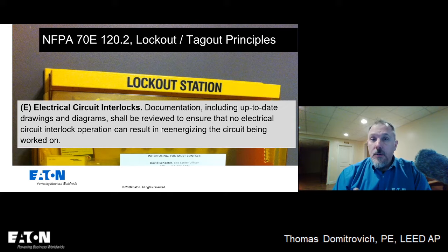So I was supposed to do a short circuit and coordination study for that facility, and we bid the project that way. When I showed up on site and found out that the drawings weren't updated, now we went into an entirely different mode, because I had to have an updated one-line diagram. We had to go back and pitch to the customer the issue that I could not do an accurate analysis without that. So then we had to change the order and the scope of the project to include a complete walk down, and we hired a group to go in and do that.